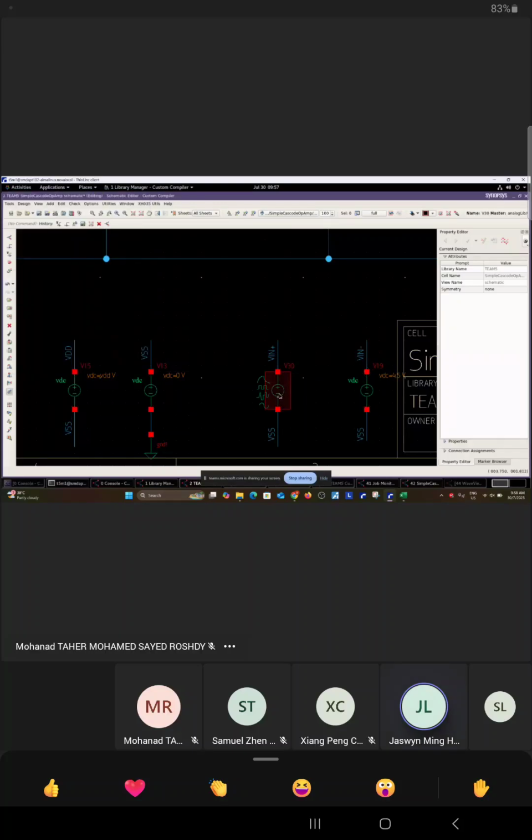Okay, now you click on it, and then edit the properties. You change the source type to AC. Let's see what happens first. For sine. Okay. Now you don't need to do any offset. So now your DC voltage is your average, which is the common mode. So your DC voltage you put VDD over 2. Type the same, small letter. Okay. Now I think you have the amplitude, the voltage amplitude, 9 or VDD.